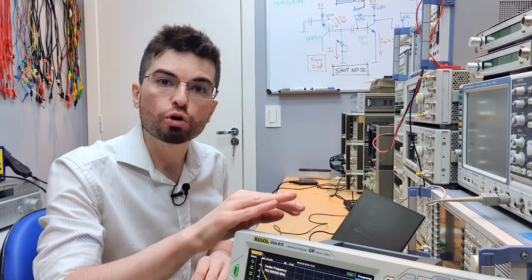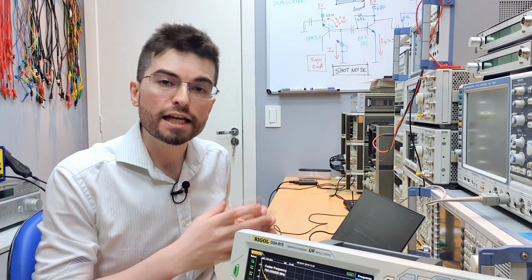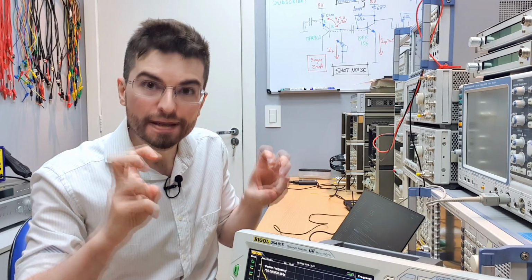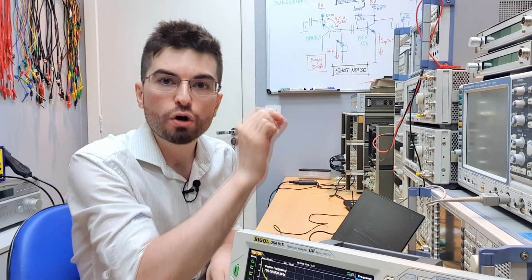So for characterizing the noise densities of the different transistors, I'm using a script that controls the spectrum analyzer. It configures the spectrum analyzer always to the correct parameters for the measurement: correct resolution bandwidth, video bandwidth, amount of averages. It configures the marker for noise function. It waits for the end of the averages, and after that it sweeps the marker automatically by the script. It goes in 5 MHz steps, getting all the data and saves it in a JSON file.